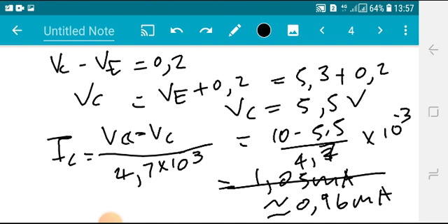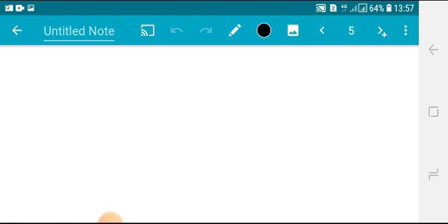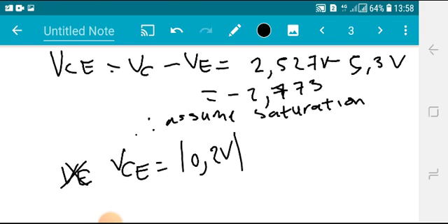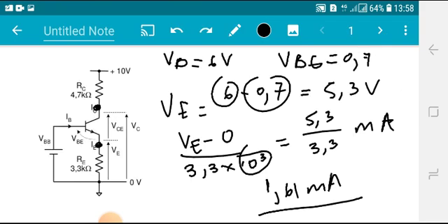And of course, here I could also work out the base current. Now I remember the total current through the BJT should be IE. So going back, just to visualize this, the current through the emitter should be the current of the base plus the current of the collector. Combine these two, one of Kirchhoff's laws, and we should get a total current going down this way.